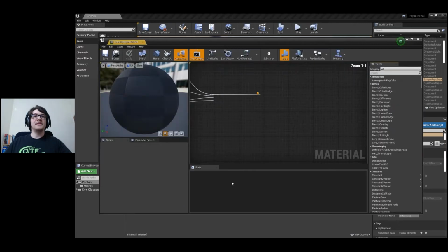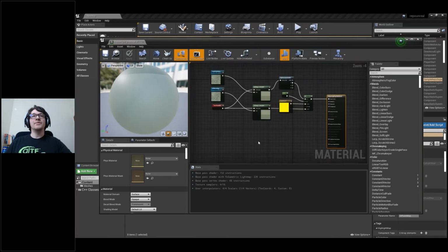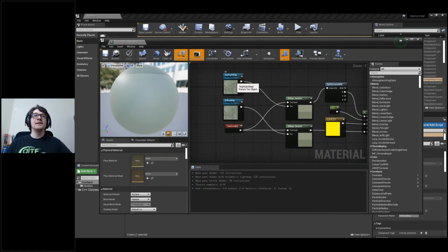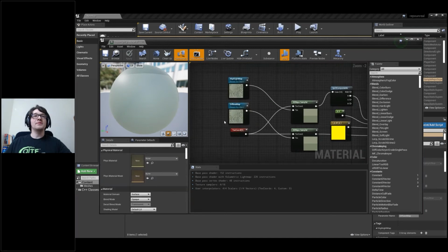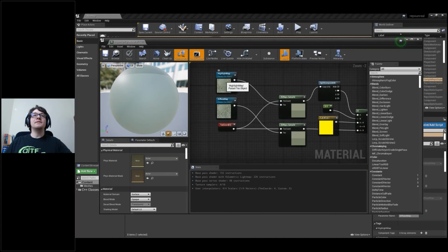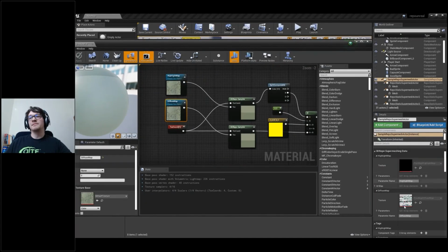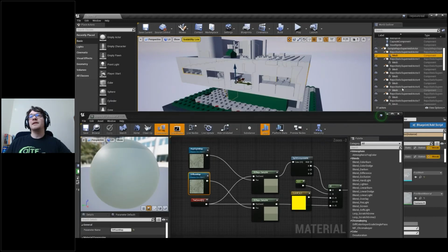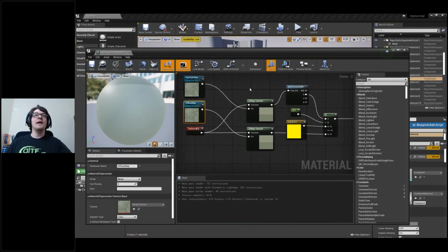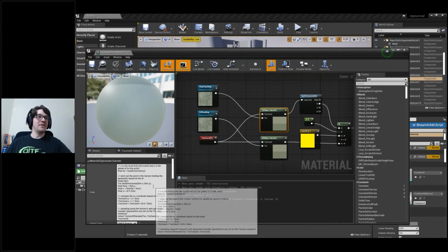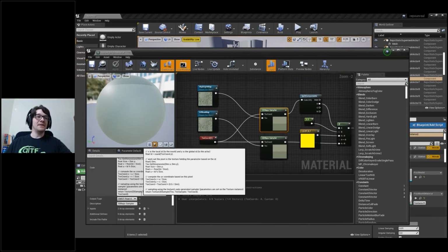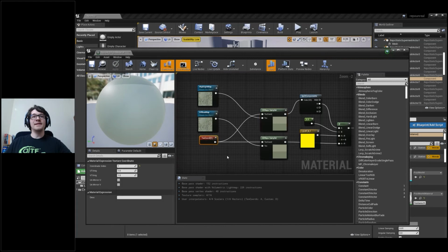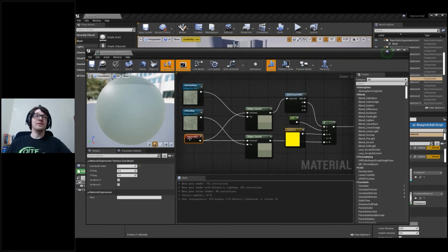So if I open one of the materials now, this is an Unreal parameterized, or dynamic instanced, material. What I have in it are 2 parameterized texture map slots, and these correspond to the textures maintained by those components on the actor. An instance of this dynamic material exists for each of the meshes in this model, and they'll all refer to the same maps. In addition to these 2 slots, I have a 3D Repo sampler, which is a custom expression node, and this little snippet of HLSL will query these maps based on the identity of a sub-object as it's read from the mesh via the texture coordinates.